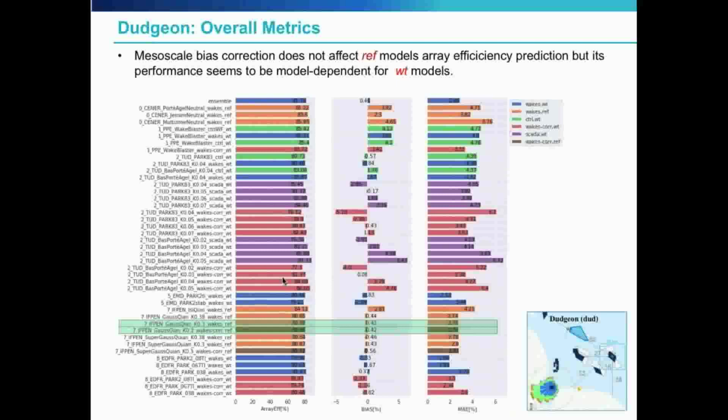The models that use homogeneous inflow don't care too much about inflow corrections because it's a linear scaling, but for those that use heterogeneous inflow, you would have to calibrate with a wake model to get something that is calibrated for the specific model.